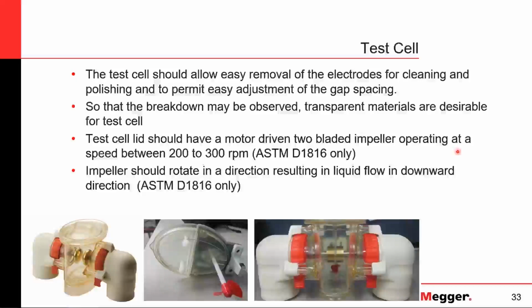Just coming back to the cleaning, you can use a dry hydrocarbon solvent like kerosene or toluene, for example. After you finish the internal cleaning of the vessel and the electrodes, make sure you don't touch the inside of the vessel or the electrodes with your bare hands. If you do, you will leave a greasy residue or moisture, contaminating your sample when you fill the vessel.